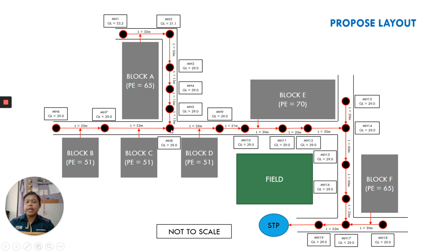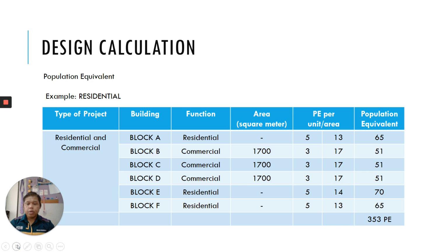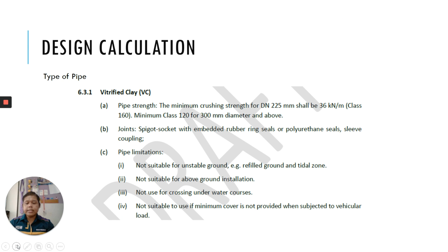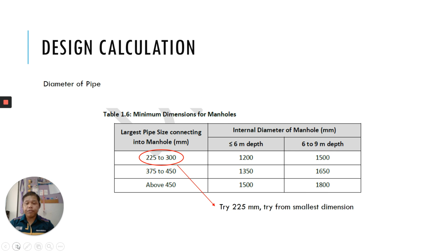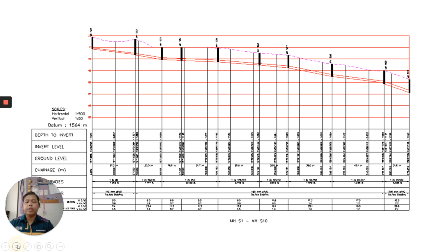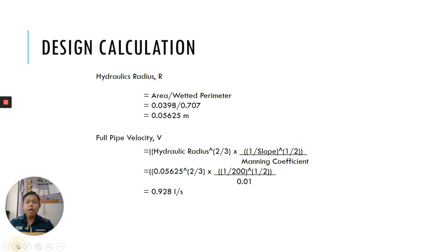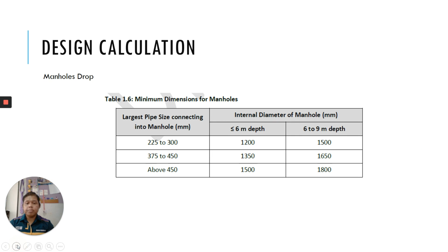It cannot be higher than manhole 7. It should be deeper than manhole 7 and manhole 5, so that the sewerage effluent will flow correctly to the STP. This is the process you have to do. Read and understand the spreadsheet carefully so you understand how to use and calculate those values.